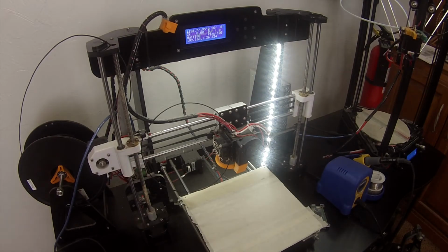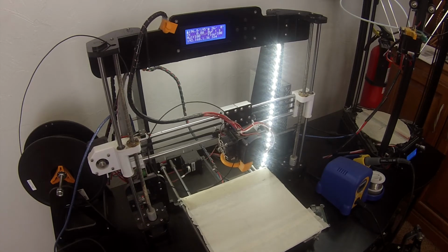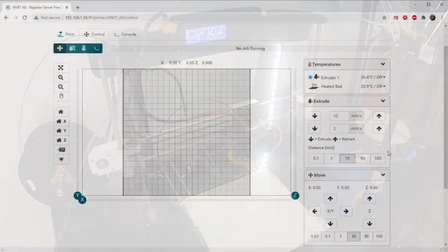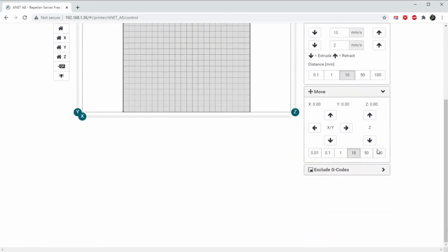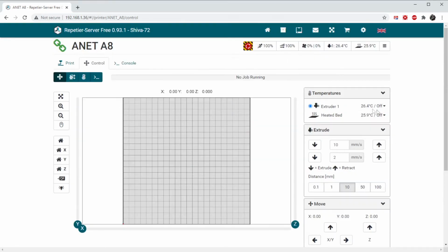It recently broke, and if you're walking up to a printer for the first time, it probably isn't loaded with filament. So to do that, you first have to heat up the extruder. You have to turn it on, which it's been a little while for this one. Instead of off, I want it set to the PLA temperature of 195 degrees Celsius. And you see, okay, it's just switched on. I can reference the screen on my printer, and yes, it's ticking up, 30 degrees C, 32 degrees C. It's heating up, and it has set 195 degrees C as the target.